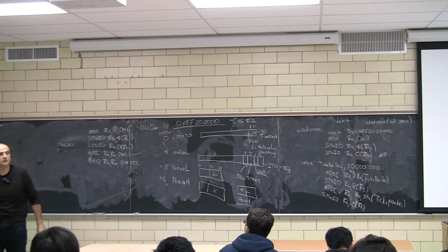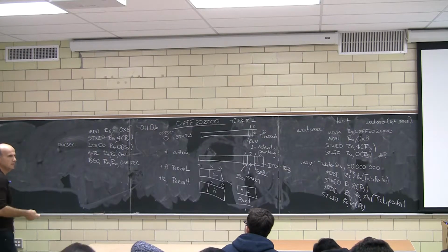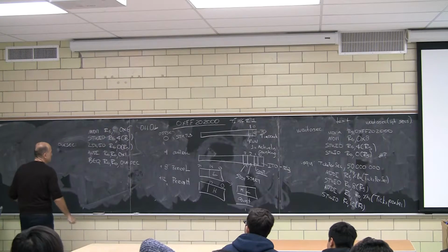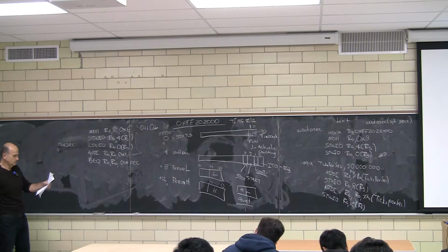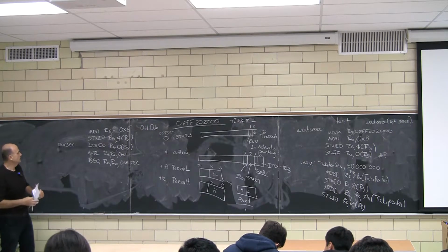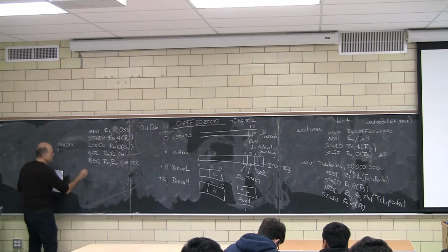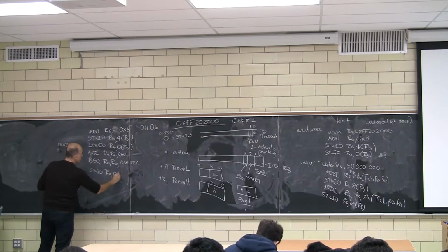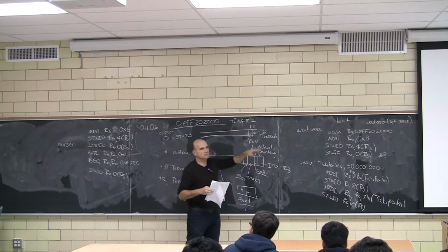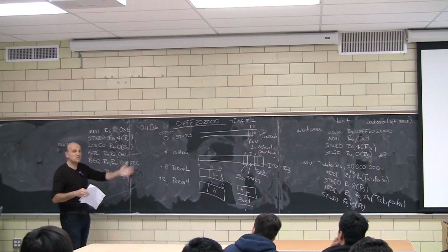This is not an infinite loop, it's a busy wait loop. We keep asking, did you time out, did you time out, did you time out. So far, so good? This is now going to fall through once that bit is set. The next thing we're going to do is a store word IO R0, 0(R5). The intention here is to set the timeout flag to 0. It means, okay, we saw that you reached a second, we did see that, but there are more seconds to count.